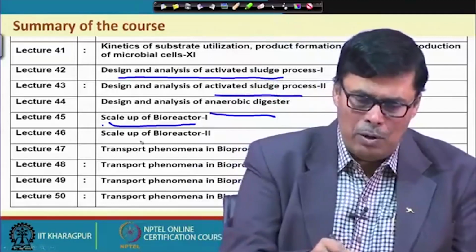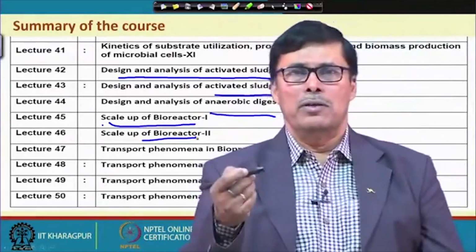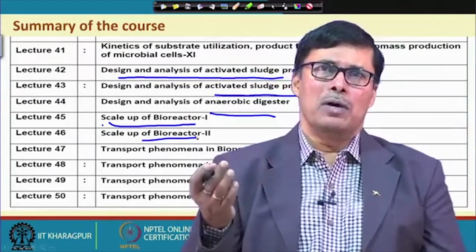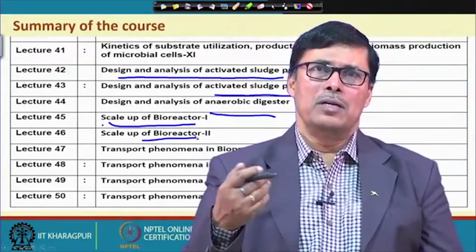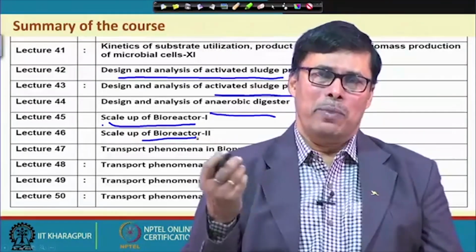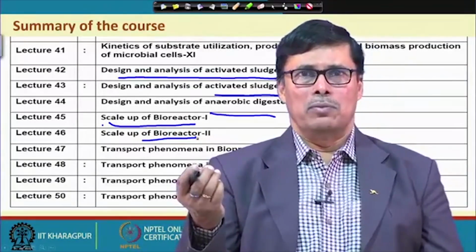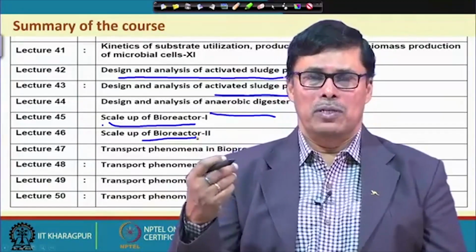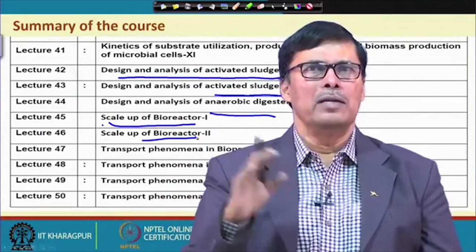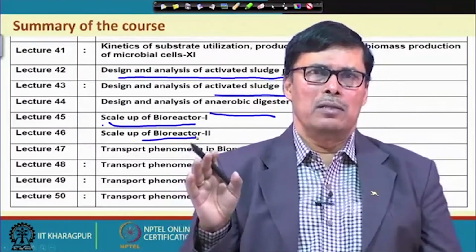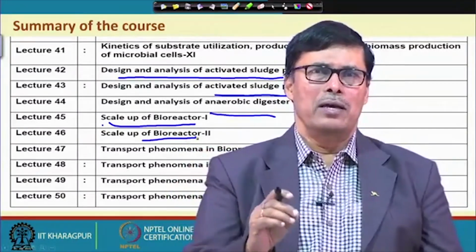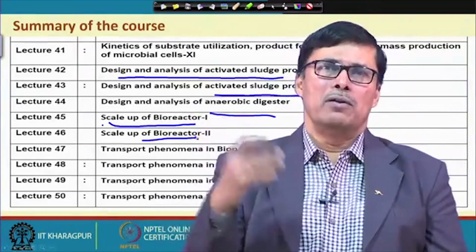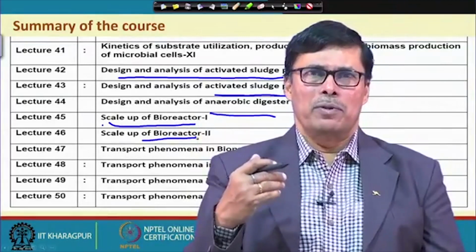And then here we also took into consideration, as I told you, the scale down of the process. Suppose in some industry, like the citric acid industry, we find out some parameters play an important role, have a significant role in increasing the productivity of the process, but we cannot directly apply it to the big fermenter. We first give a trial in the small fermenter, and if we are satisfied, then and only then can we go for the bigger fermentation process.